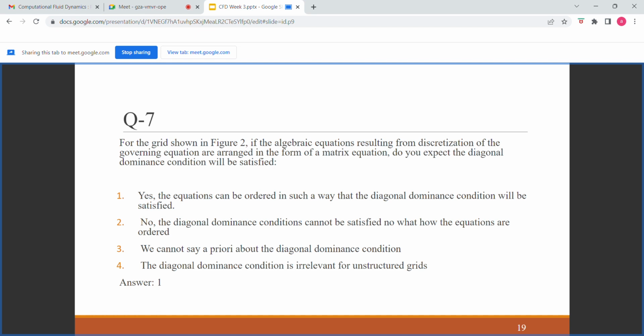Basically, in CFD, what we do is discretize the given system and get a number of algebraic equations, which we solve using some numerical approach. From the numerical approach we get the solutions. Most numerical techniques check for diagonal dominance to ensure convergence in those problems.